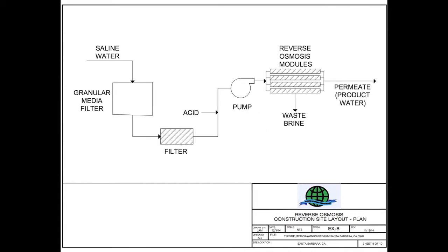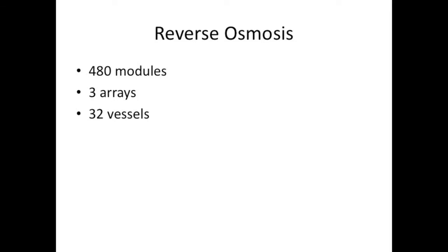The influent water enters the reverse osmosis process and is pressurized along a semi-permeable membrane and enters the exiting piping as pure water. 50% of the 14 million gallons per day of water fed into the system will be discharged as saline back into the Pacific Ocean. This stage is the most energy-intensive step of the treatment process because of the large amount of pressure needed to push the water through the microscopic pores in its membrane.